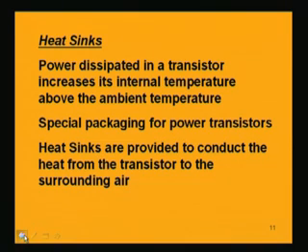As this power dissipation is invariably associated with temperature increase, or the transistor device being heated up, there must be some schemes for reducing the heat. That is why heat sinks are used. So heat sinks are used with the power transistors to take care of this heating caused by the high power dissipation.